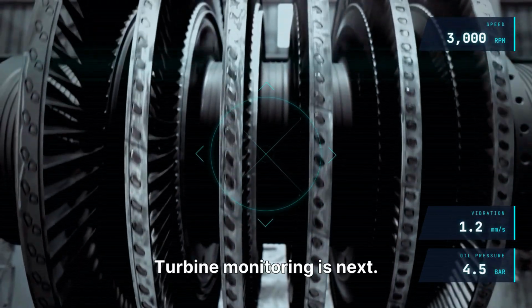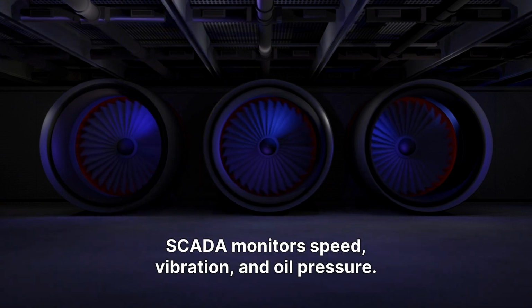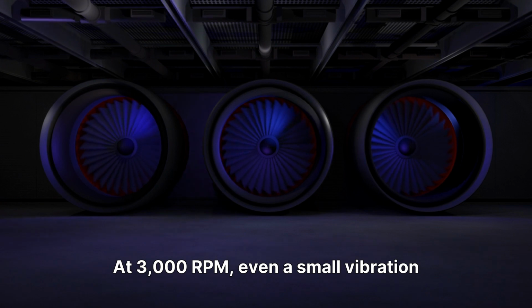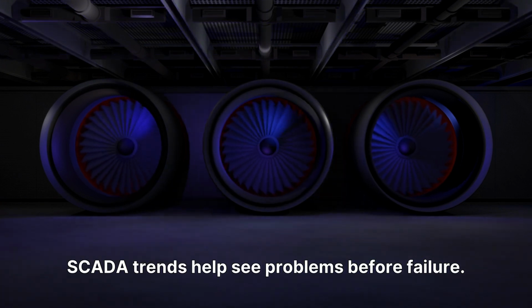Turbine monitoring is next. The turbine is expensive. SCADA monitors speed, vibration, and oil pressure. At 3,000 revolutions per minute, even a small vibration increase is serious. SCADA trends help see problems before failure.